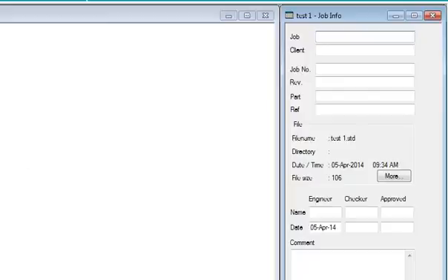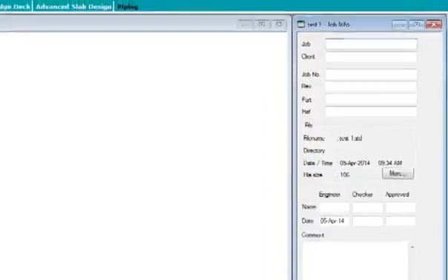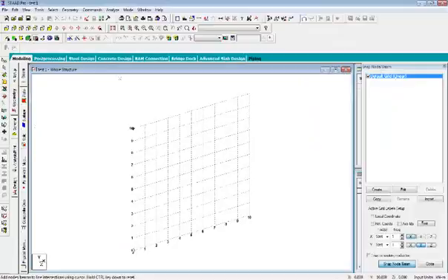The first actual thing that we are going to do is the geometry. Fine. Now this comes in the y cross x matrix, meaning y and x coordinates. Here you are just limited to placing the nodes. Then what is a node? The first thing that we learn in STAAD is the node. Any connection, junction or point of any two members, maybe two beams, maybe two columns, is known as a node.